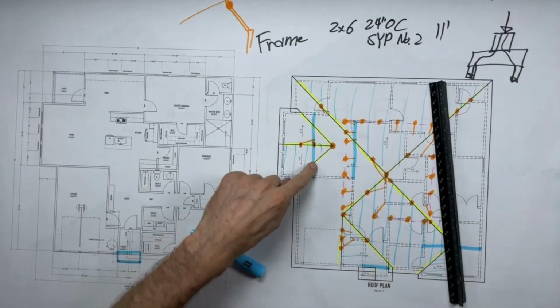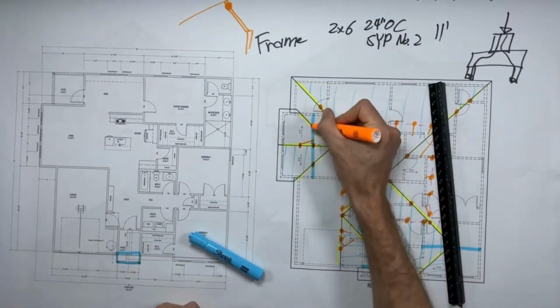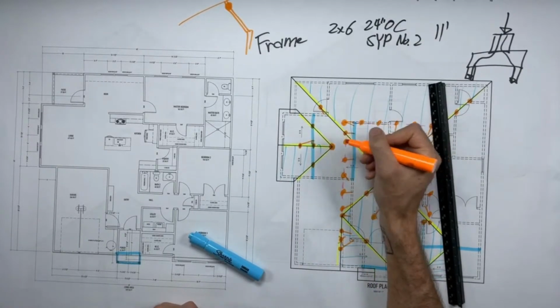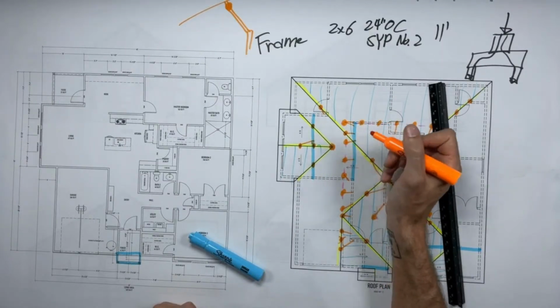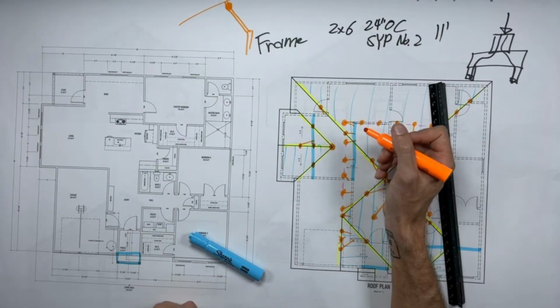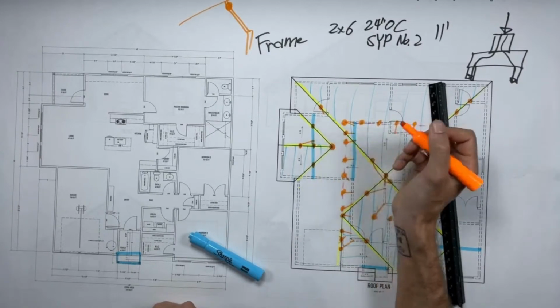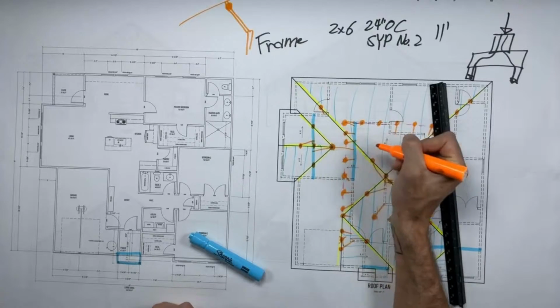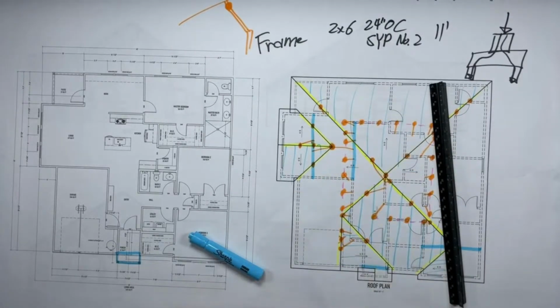Okay. So that beam will catch the support for these valleys. It'll catch the support for the ridge. And this one could probably, it's not in a great place. And we're not that much higher above it. So we could go back this way. Honestly, if it was me, these beams are at the same height. I'd probably put a brace this way and then a brace that way. I would double brace that. And then everything would be pretty hunky dory. That's what I would do.